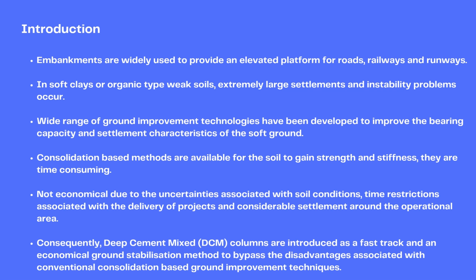Because of that, these methods can be uneconomical in difficult ground conditions. And also, time restrictions in projects may be unfavorable for these consolidation based methods because of the lengthy times required for consolidation.